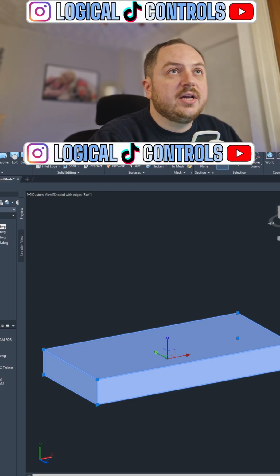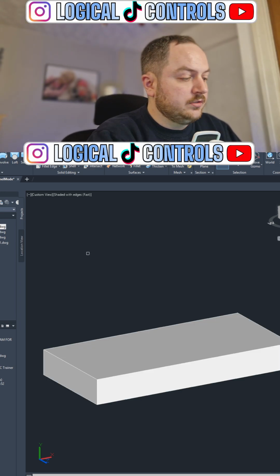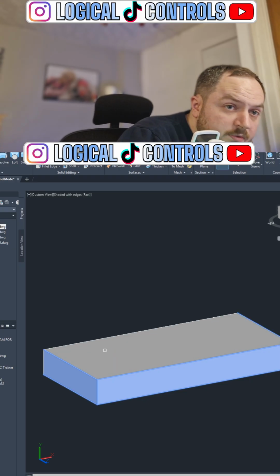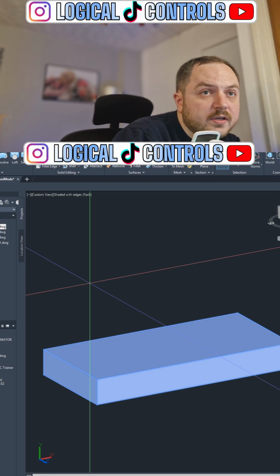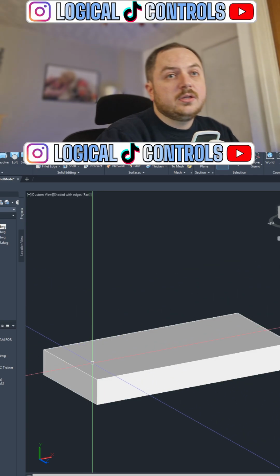I'm going to now shell that, so it's, at the minute it's just a solid slab. I'm going to shell it so it's 2mm. What's it asking me for there? Remove faces. I don't want to remove faces. Enter the shell distance 2. I think that should do it.